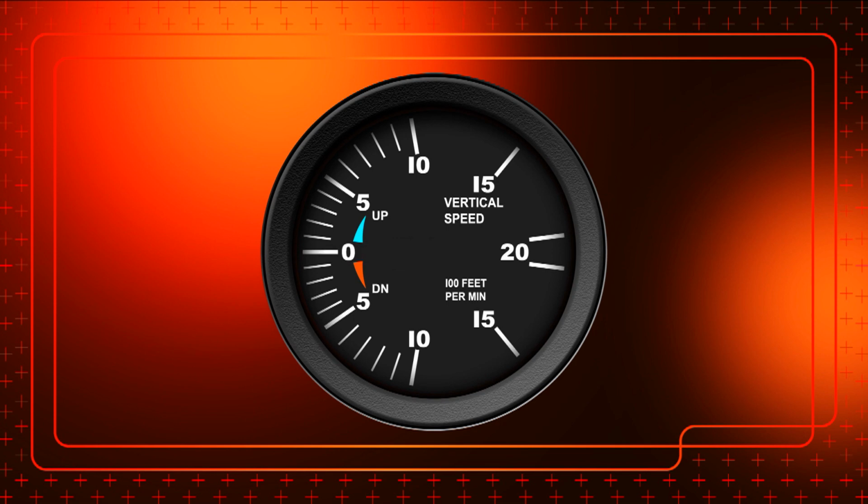We will now move on to the individual scale markings on the display of this instrument and show you what they represent. You will see that in both the climb and descent portions, there are identical scale markings with numbers next to them. These scales represent an exact rate of either climb or descent, which are measured in hundreds of feet per minute. As well as these scales, there is an indication pointer that will rotate over these scales to indicate the exact rate of either climb or descent to the pilot.